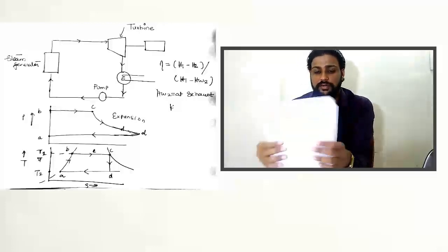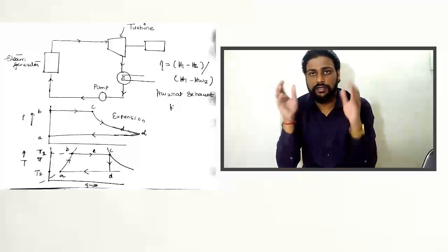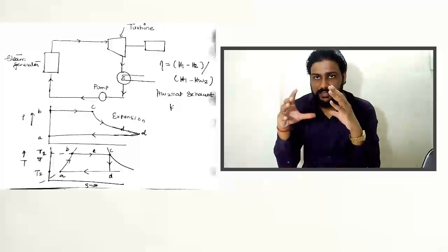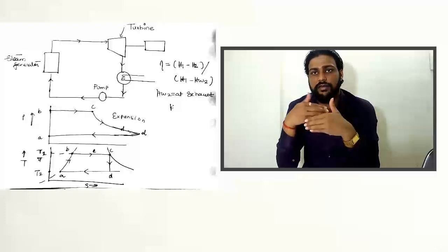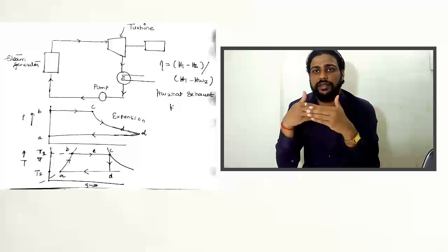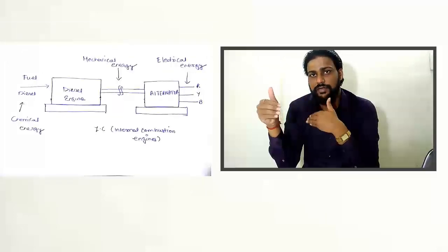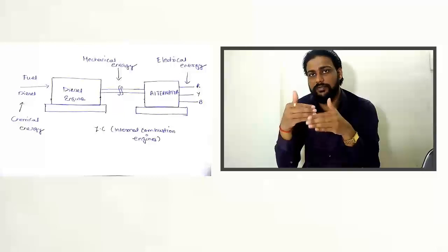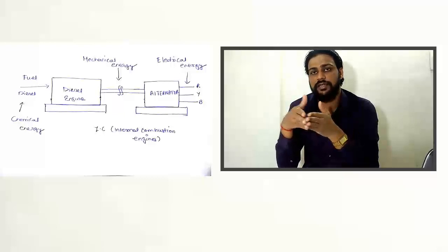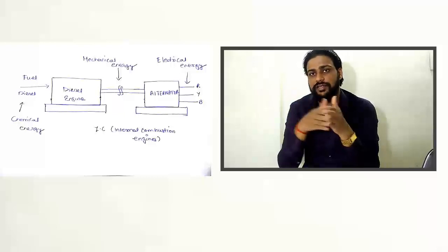Again, if you are talking about the diesel power plant, it will have a diesel engine. What you are doing is supplying diesel as a fuel, and this engine will produce rotation of the shaft, like the engine of your car or bike is rotating. In a similar way, the chemical energy from the fuel, which is the diesel, will be converted to heat energy, the heat energy will produce work, and the work will be converted from mechanical energy to electrical energy via the coupled alternator.